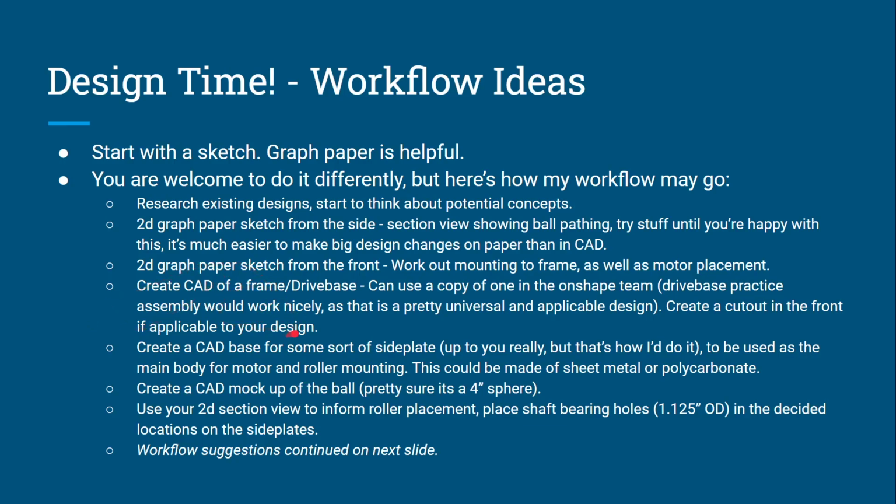Right, so you'd create CAD for some sort of side plate, and then you would have places to mount bearings for your rollers, and then one place to mount your motor gearbox, right, a versaplanetary. So that's how I do it, right, some sort of aluminum side plate, or if you can find a common off-the-shelf option, that would be good too.